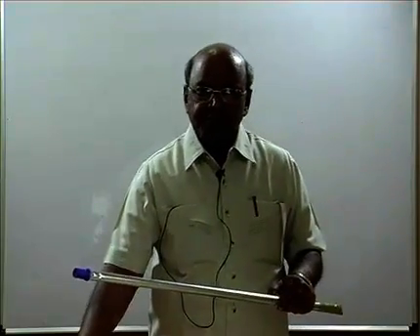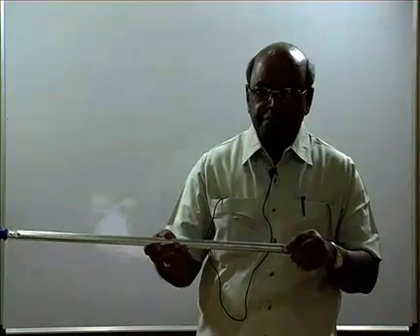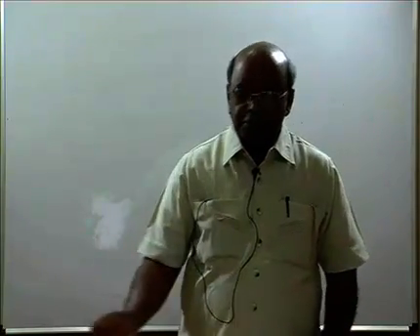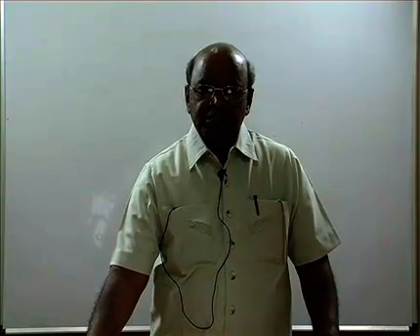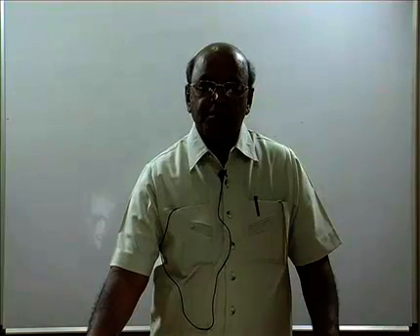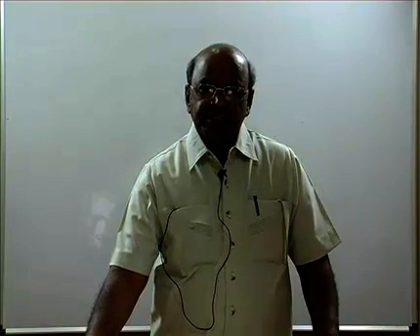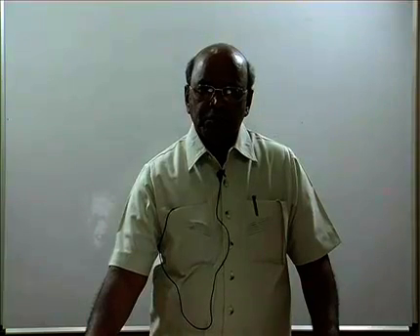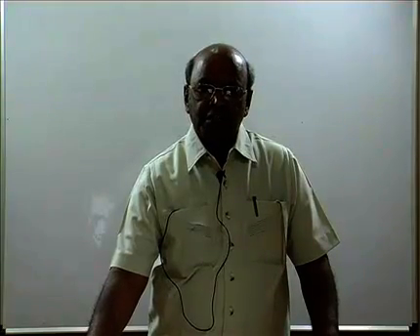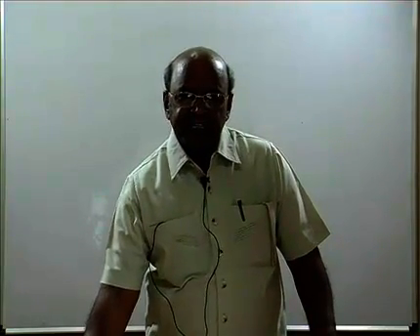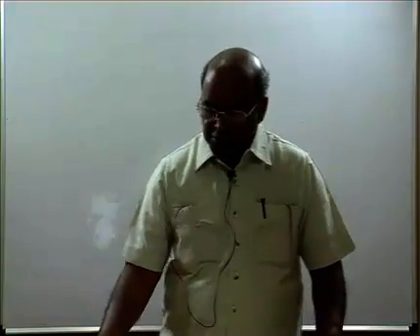One thing you can observe from this, both the projections, front view as well as top view, have the true length, that means the same length as that of the original object. So when the straight line is parallel to both, both projections are parallel to XY, that is number one. Another point is both projections have true lengths. So that is what you should remember when the straight line is in the first quadrant and parallel to both. Now let us take the second case.